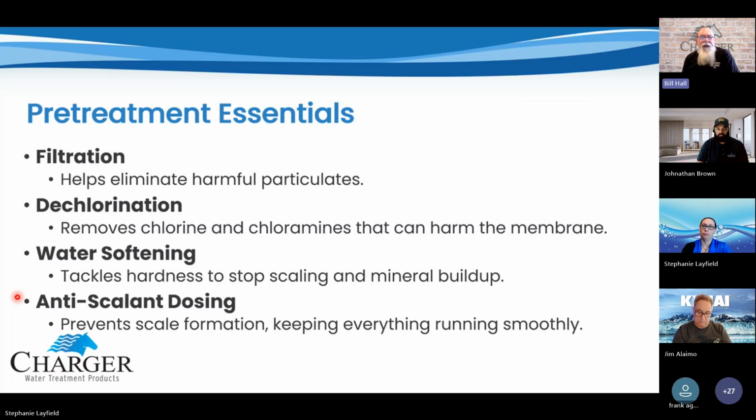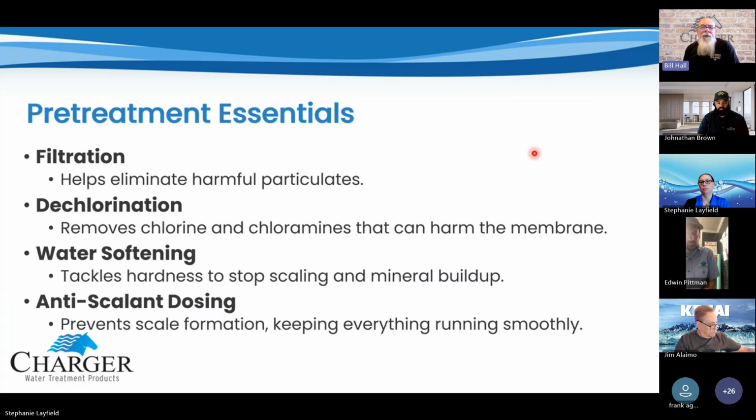the RO manufacturers a lot of times will use a computer program like ROSA or something like that that you can plug all the parameters into, and they can tell you whether anti-scalant is the way to go or not. And if it is, they can tell you how to dose it. They'll tell you how to dilute the product, and if you're going to dilute it, how much to dose. They can make sure that you don't put too much in there and plug things up. But like Stephanie's point, test, test, test.